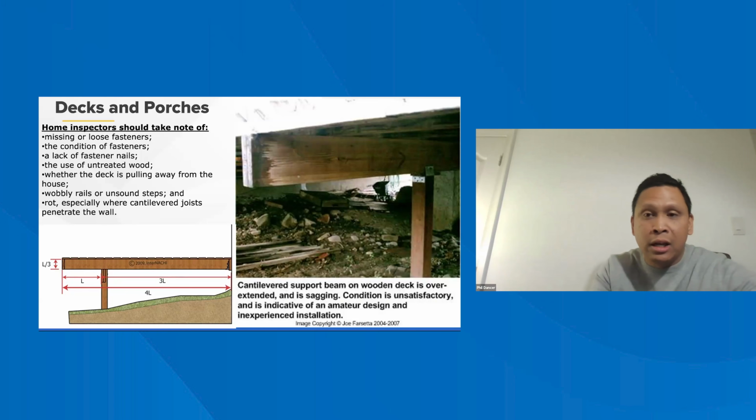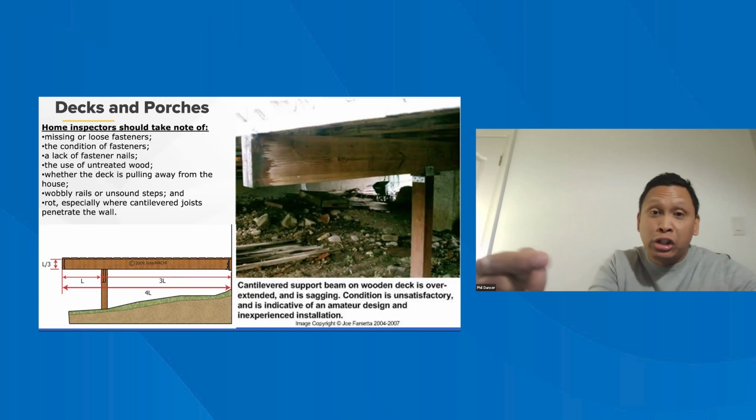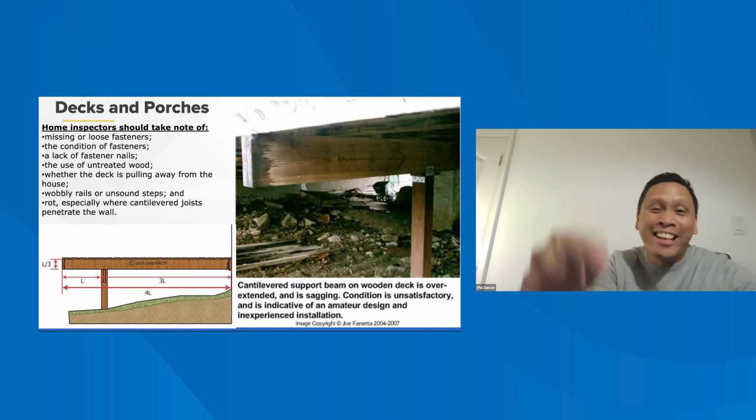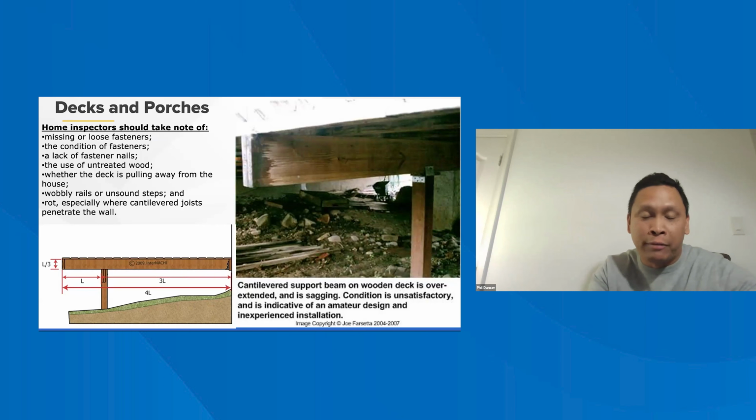And sometimes you'll actually see a contractor installing what's supposed to be a shear diagonal nail sideways as opposed to diagonal, and then into the carrying or the supporting framing, depending on who the manufacturer is. I believe Simpson Strong-Tie calls the two pieces of framing carrying and carried members, and then MiTek will call them supporting and supported.